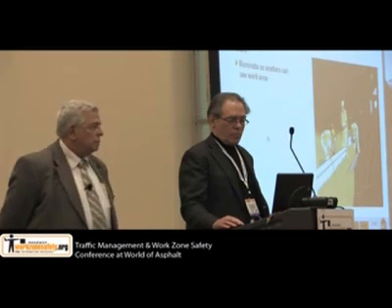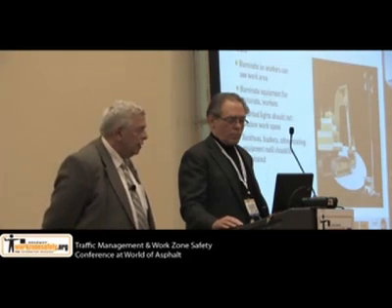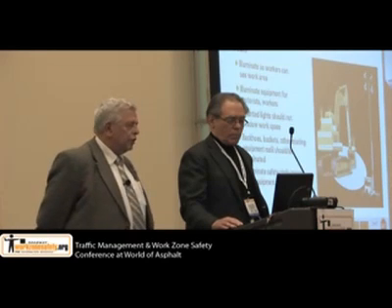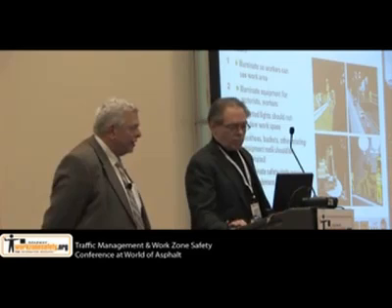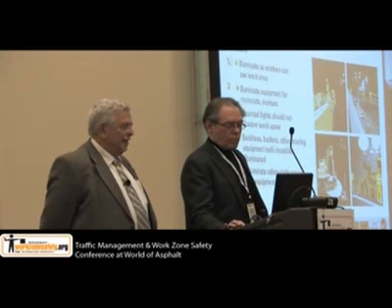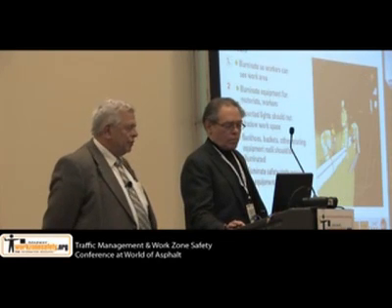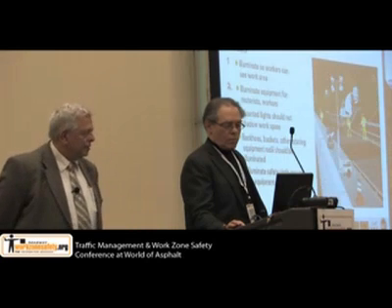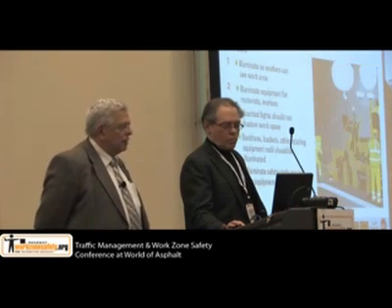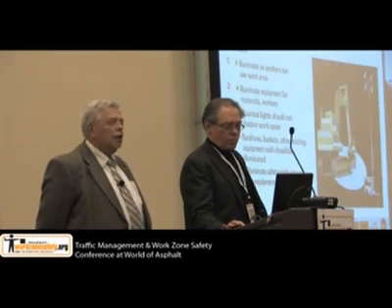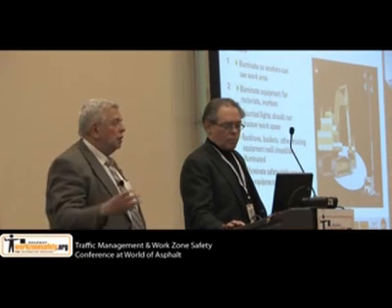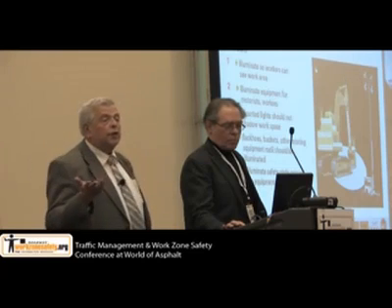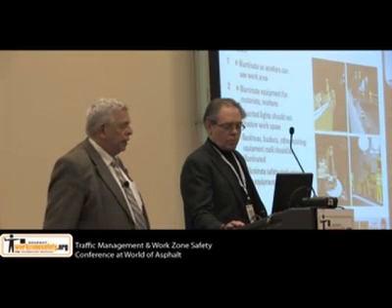What should be illuminated? Obviously, the workers can see the work area, the motorists can see the workers, the mounted lights do not put you in shadows, and the backhoes, buckets, and other equipment not only should be illuminated, but the illumination should be around the safety circle around the equipment, so that you can see it.